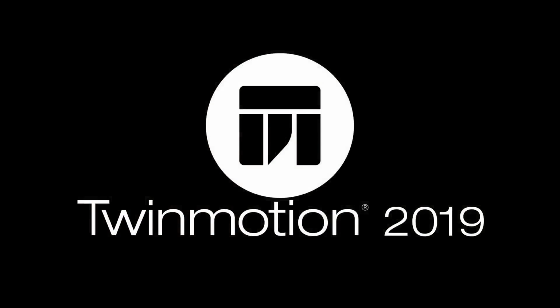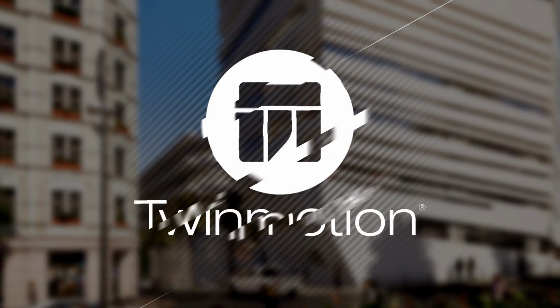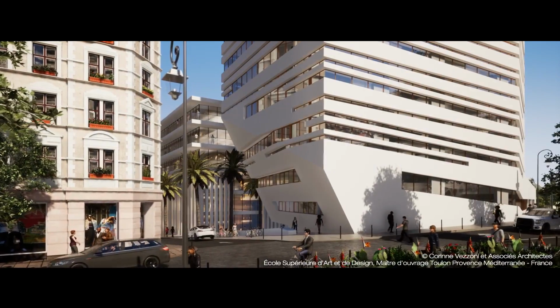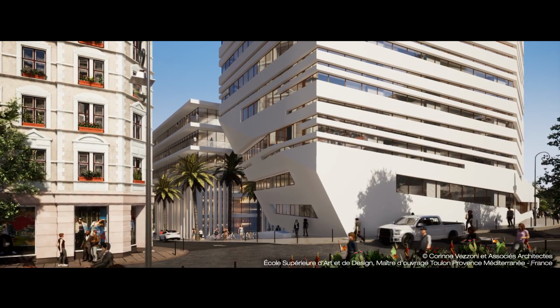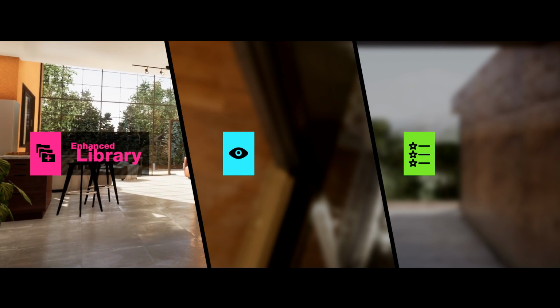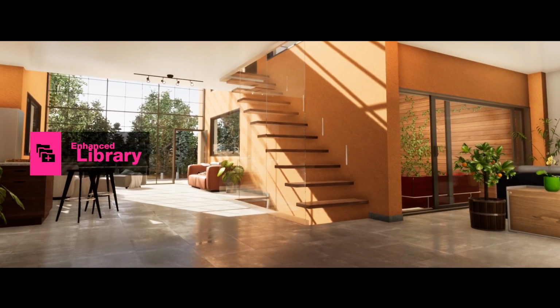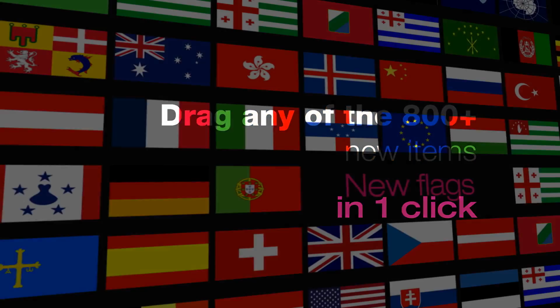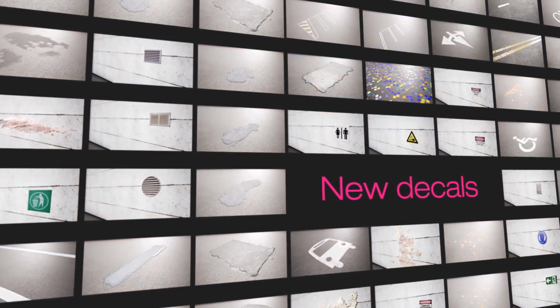Is the sun and shadow system based on real-world coordinates, and can I change it? Yes, so there is an option called the localization option, where you have some kind of Google map where you can precisely geolocalize your project and retrieve the correct position and orientation of the sun, so you can make a real sun study of your project. So you can place your project wherever you want, and you can have the correct position of the sun.